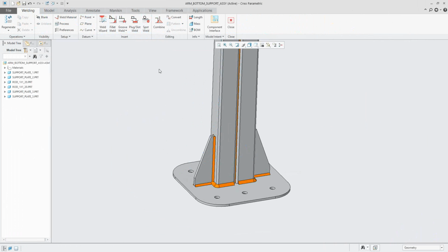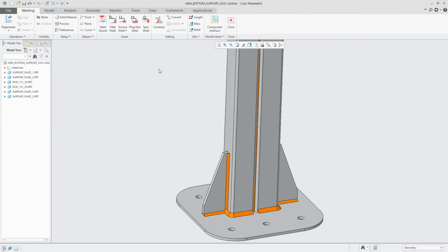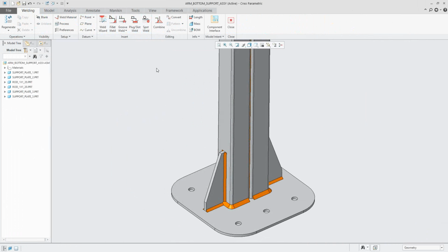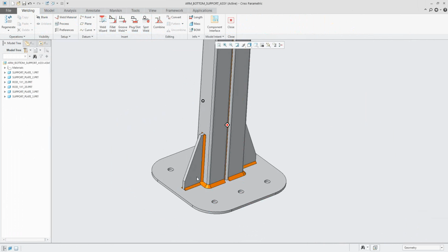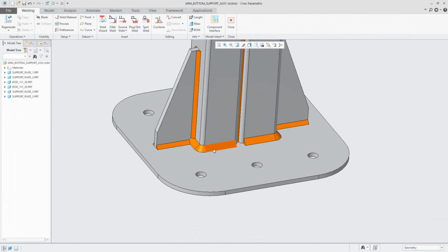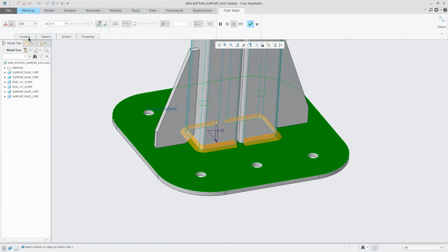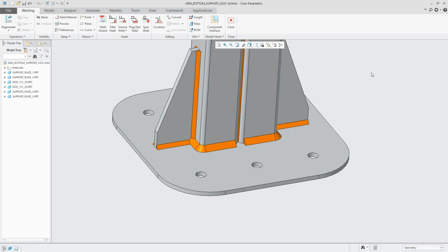The only thing that's really changed as far as the welds is the ability to convert those to a solid weld, rather than just having surfaces. So yeah, they could be staggered if need be. That's what this icon here allows us to do, have staggered welds, and allows you to define the placement and so on. Good question.